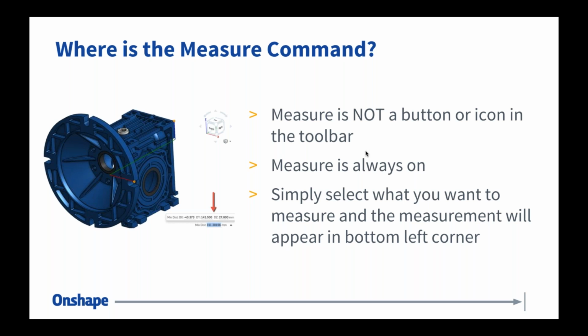If you had to take away one thing from this webinar, it would be there's not a button that you're going to go click on first to enable measure, right? So not a button, not an icon in the toolbar. It's not something that you're going to find. You just simply click on the thing that you want to measure. So measure is always on, and you select the thing that you want to measure.